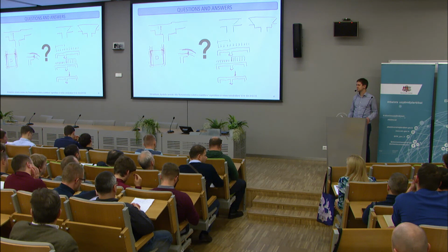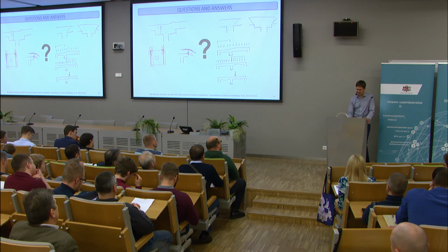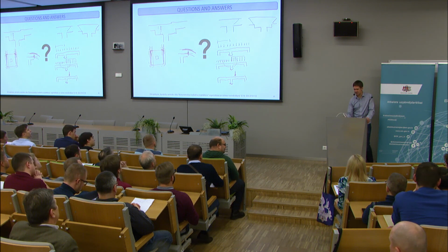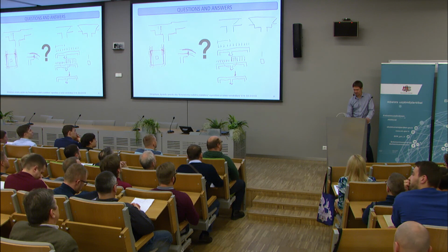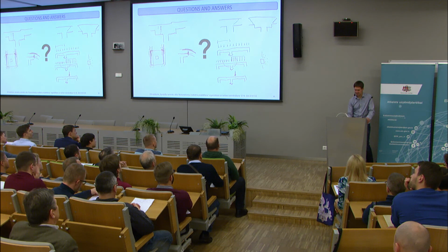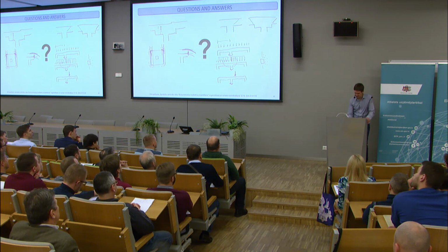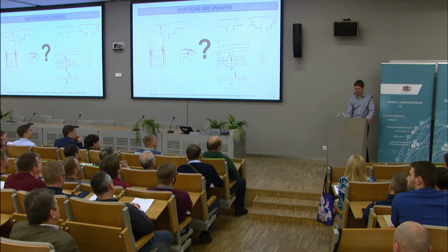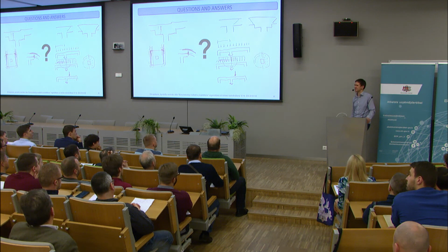symmetrical, the results differ very much. Yeah, I think in this case, when the shear force is higher on one side, I could design the two halves differently. I could put a larger shear stress on the whole perimeter, or a larger force on the whole slab, and then design one half for the larger load and the other half for the smaller load. But I guess in practice I would just put more reinforcement around the whole slab.